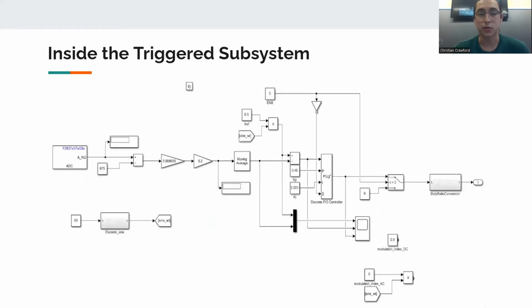To do this with the sensor board, we connect the I sensor from the J4 pin to the ADC, which is at J3 pin 29, to get the closed loop control waveform. Within this test, we had to change our offset, our gain, and our KP and KI values to achieve a pretty good signal.